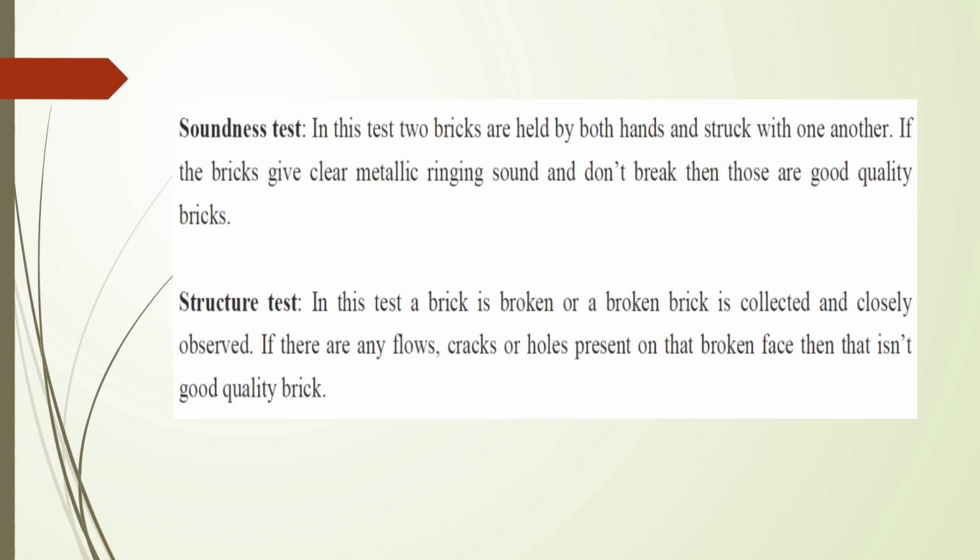Soundness test. In this test, two bricks are held by both hands and struck with one another. If these bricks give clear metallic ringing sound and don't break, then those are good quality bricks.